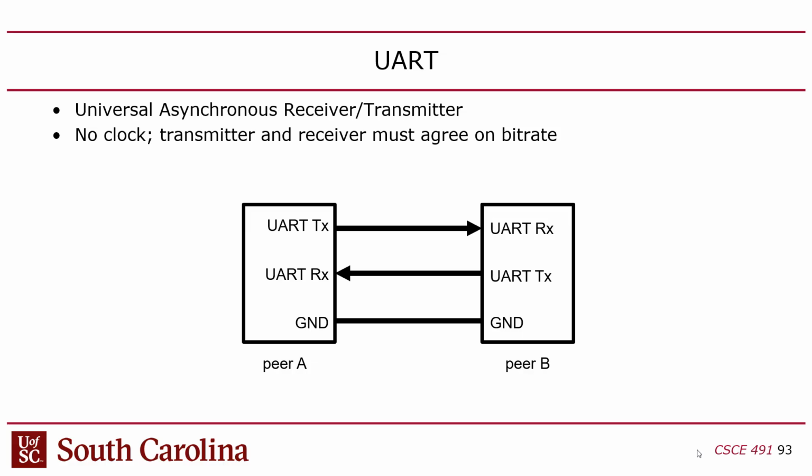But the way that you would talk to the ESP8266 to actually do the Wi-Fi stuff was through text, UART. They called them AT commands, like a modem. I don't know why they did that. That's insane, because there's so much overhead in having to encode in ASCII. But anyway, UART is usually used for text.